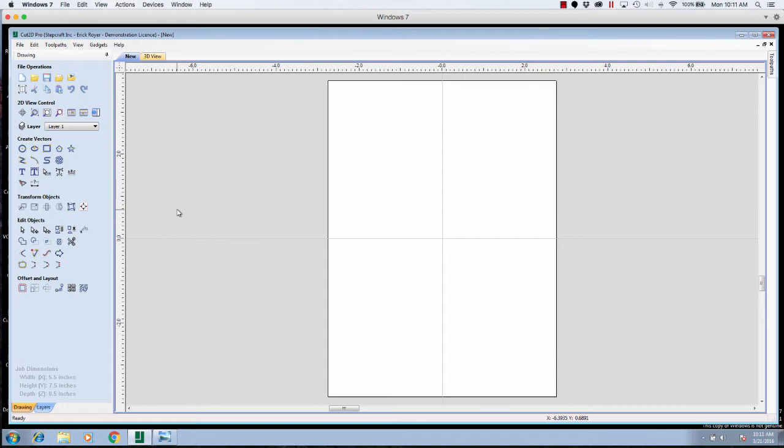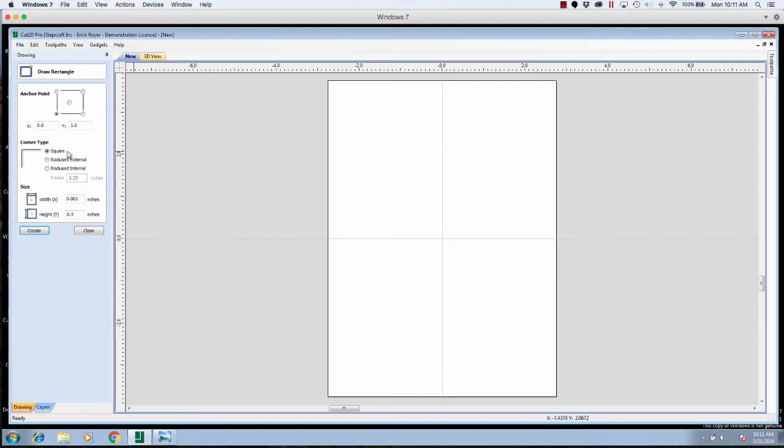So what I'm going to do here first is establish the border of the tiles. In this case, we are going to go 5.4 inches by 5.4 inches. Now, the reason I chose 5.4 is because my workspace is 5.5, and I didn't want to use the factory edge. I wanted to cut in a little bit all the way around, so I'm making my own edges with my end mill.